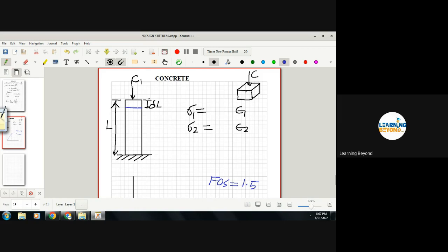The width of the beam is, let's say, 230 and the depth is 600. The column also has similar sizes. If you consider the slab, the thickness is 150 mm and the total area is, let's say, 4 meter by 4 meter. So it is not exactly a cube. Whatever members we are designing, they are not cubes. They have longer length, more area for slabs, like that.